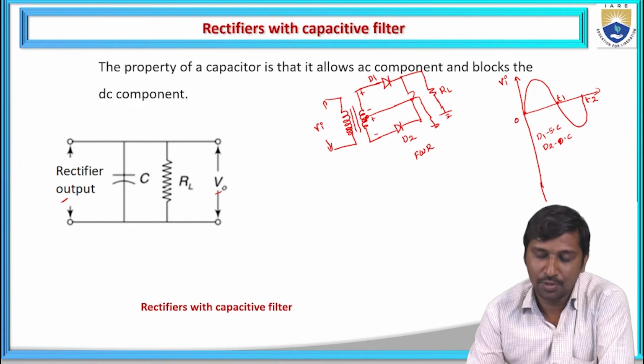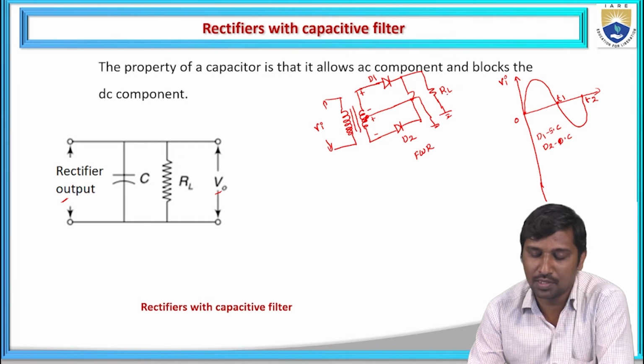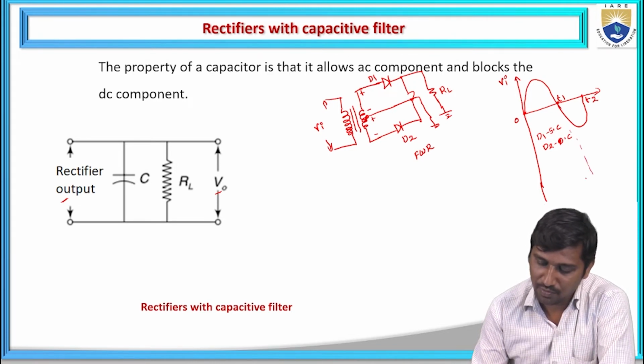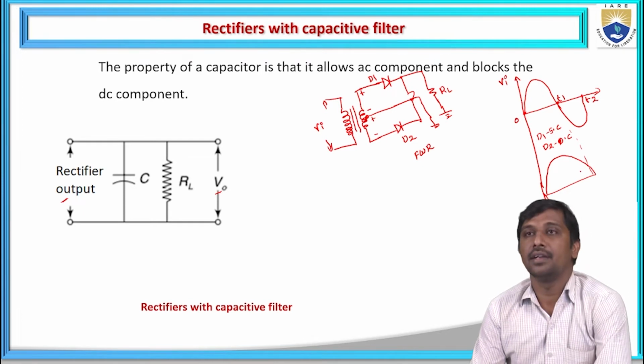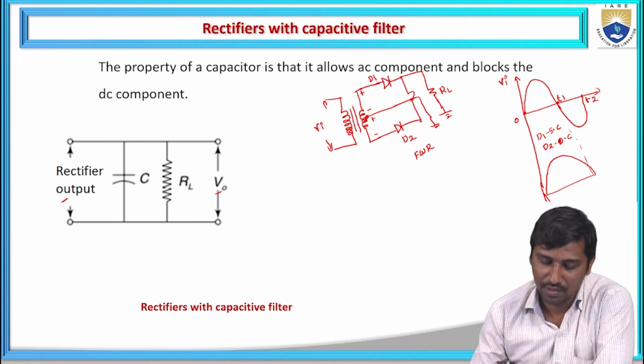Since the diode D2 is an open circuit, the maximum current flows through D1 towards the load resistance. The current flowing across the load resistance is in the same direction, hence the maximum current passes through the D1 path towards the load resistance.